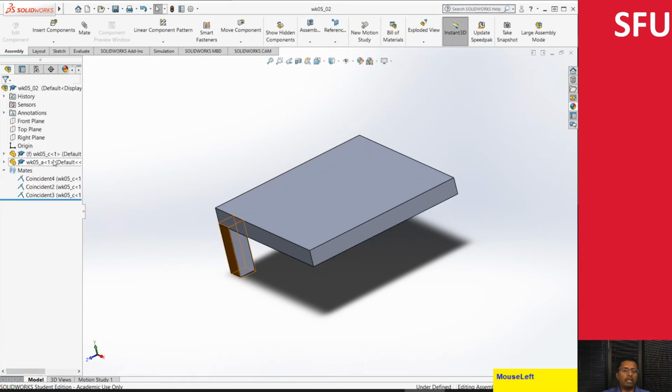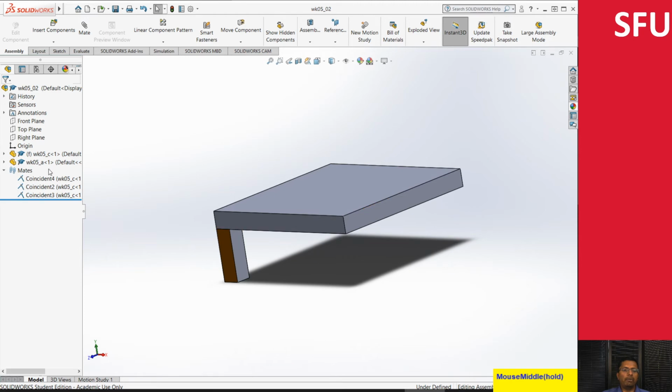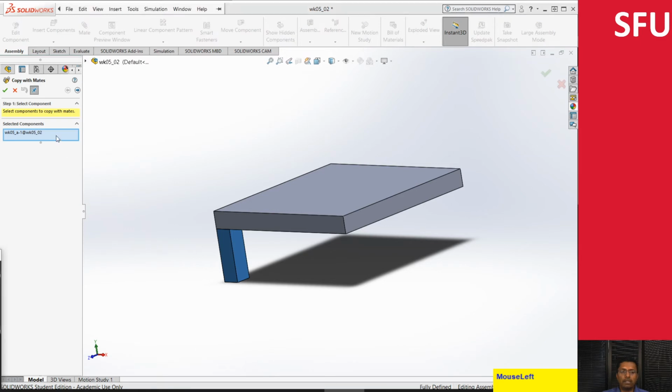Or the other option is I can copy my parts with mate, or I can do more interesting stuff like creating a linear pattern. The linear pattern is probably fairly straightforward, but let's look at copying this with mates. We right click, and if we go through these menus, just before delete, we have copy with mates. Notice that it's asking me to select the component here. This would be useful if I hadn't already selected the components before hitting copy with mate. You can also get to copy with mate from the menu option. In this case, this would be empty, where you would actually select one or two.